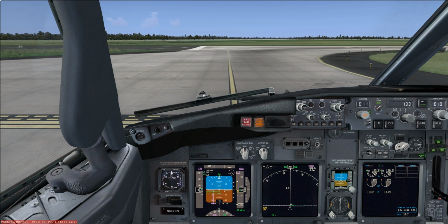Another cause of wind shear is a phenomenon known as virga. It follows the same principle as a thunderstorm, except that the rain evaporates before it reaches the ground. Now, how do you avoid wind shear? The first step is to know the clues and tell when wind shear might be present. Wind shear is present, as I said before, in thunderstorm activity and virga.